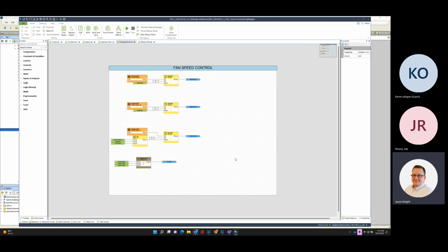So remember when current switches came out and originally you could read the actual amps, and then they just went to go no goes. And then they went to a VFD current switch that had a button on it, and you would set the VFD in 10% speed increments from 0 to 100 and keep pushing the button every time you get to 10. So it would learn the actual amperage of the motor. You go up and then you go back down.